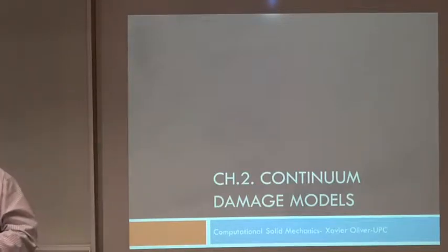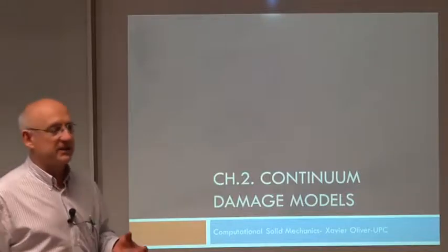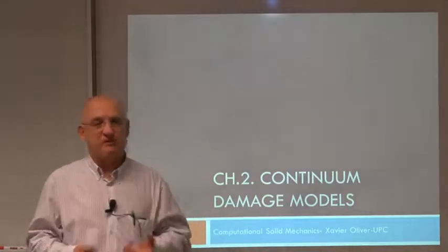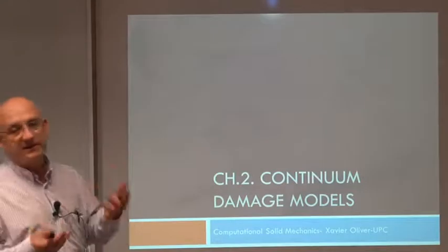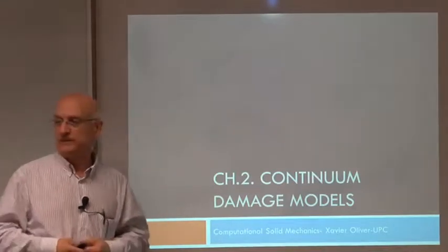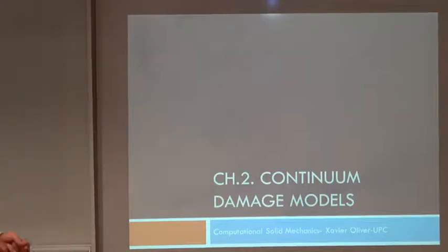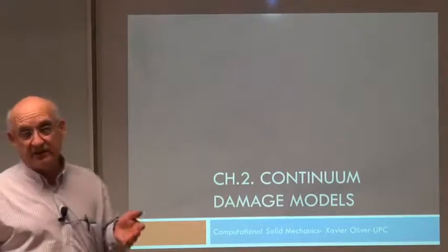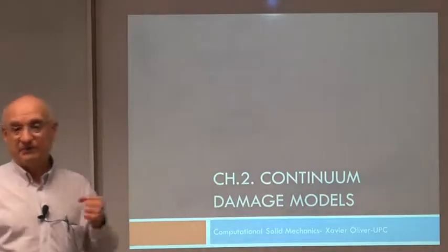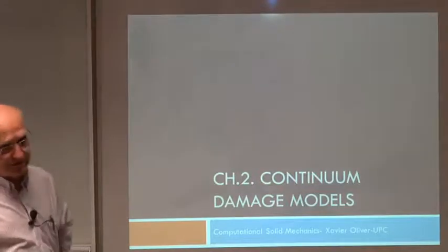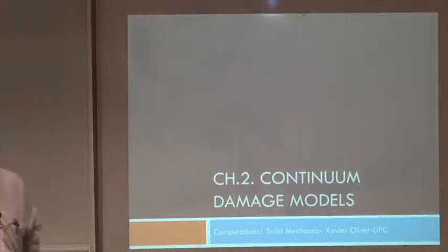Typically, materials which are called geomaterials, materials that have a microstructure or a mesostructure made of a matrix and some aggregates or little particles, typically concrete in civil engineering, but also some materials in soil mechanics are frequently modeled with this kind of models, and also some less traditional materials are now modeled with continuum damage models.